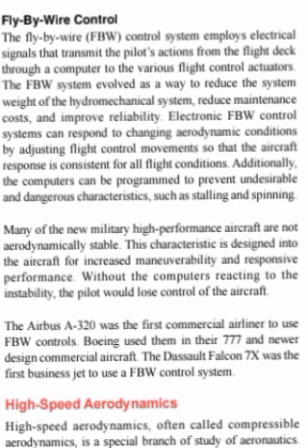Many of the new military high-performance aircraft are not aerodynamically stable. This characteristic is designed into the aircraft for increased maneuverability and responsive performance. Without the computers reacting to the instability, the pilot would lose control of the aircraft. The Airbus A320 was the first commercial airliner to use fly-by-wire controls. Boeing used